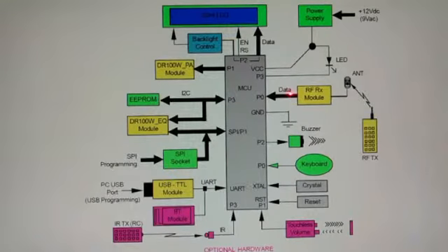We have here 4-bit data composed of D0, D1, D2, and D3, in parallel, interfaced to the MCU. When we send the signal and it is received by the RF module, this 4-bit data will have a logic level, either 0 or 1, or combinations of 0 and 1, and the MCU will read this 4-bit data and interpret the logic 0s and 1s.